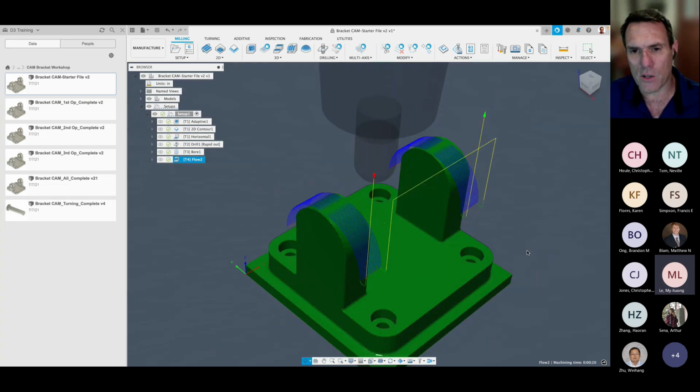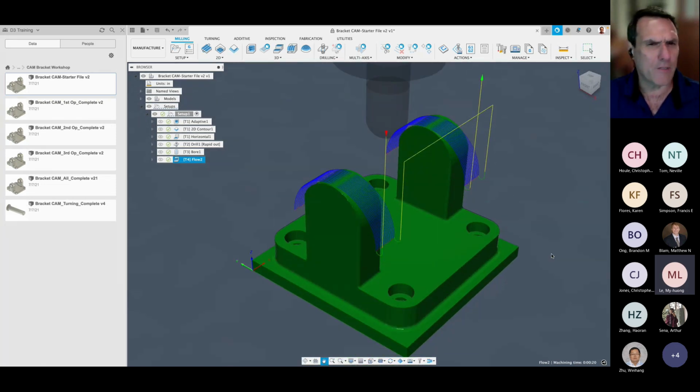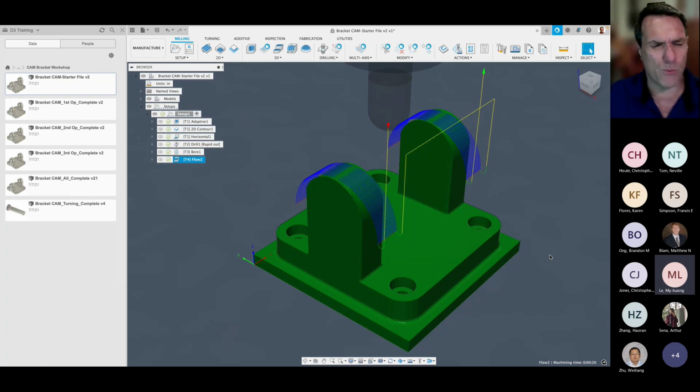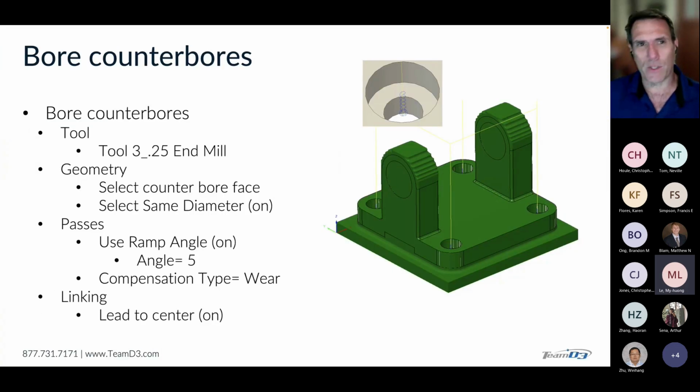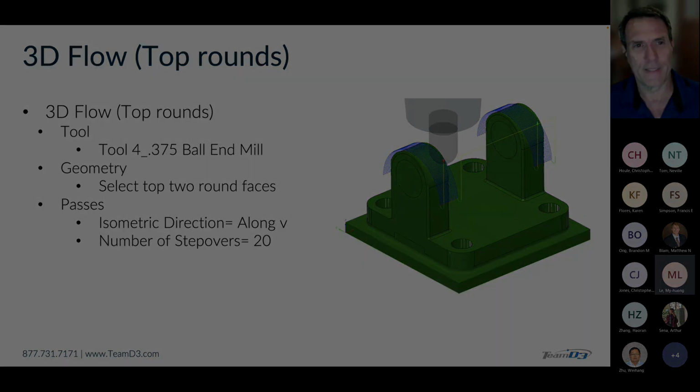So that's another thing that's great about these previews is if you see a toolpath result that you really don't think is quite right, you might want to check a variable, or in this case, look for something fairly obvious, which is picking the wrong tool.